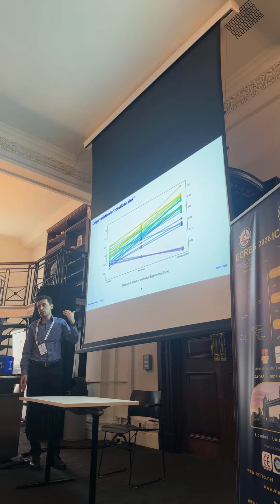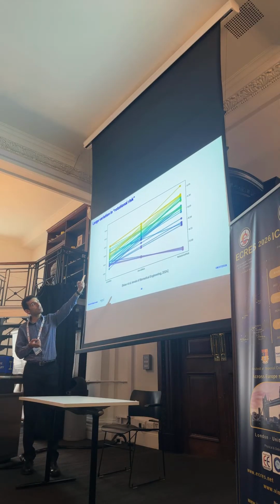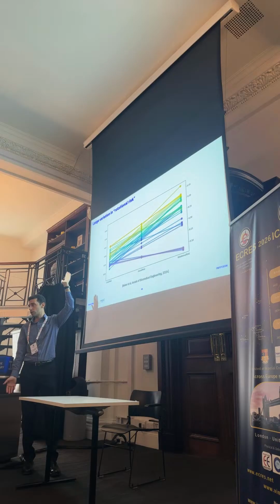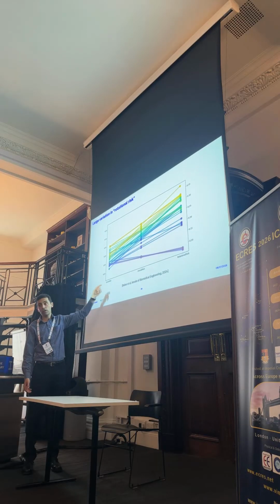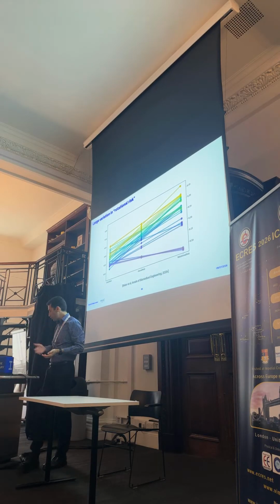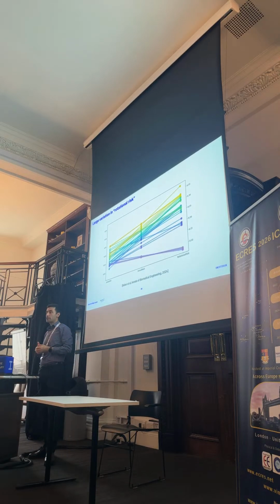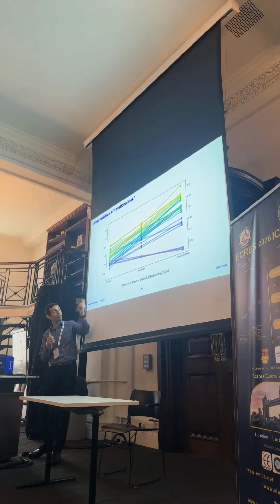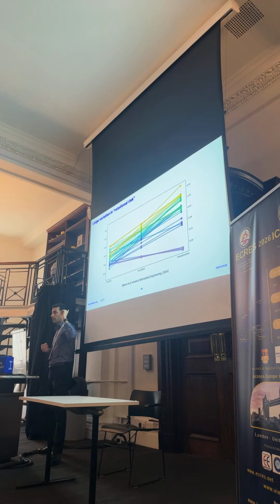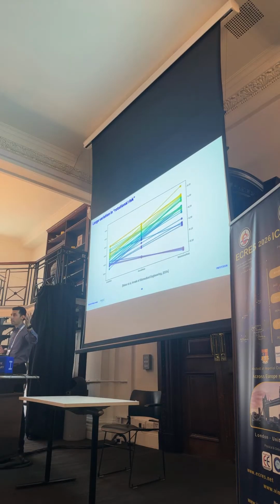And one of the reasons we thought could be that standards are only enforcing this and not that. So manufacturers do not have to control rotational risk. And as a result, we end up with solutions that have very different rotational properties. But when it comes to linear risk, they are optimized. I was talking to manufacturers, and they were telling me that they spend almost 80–90% of their budget to optimize their helmets for the standard, which is the linear risk. Which is a shame, because we know rotational risk is important, but we see so much disparity.